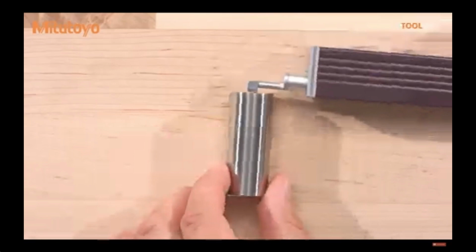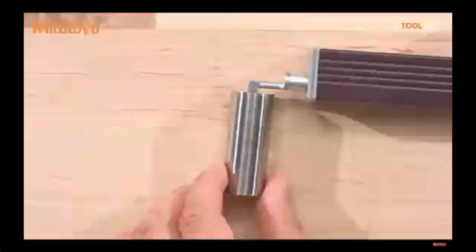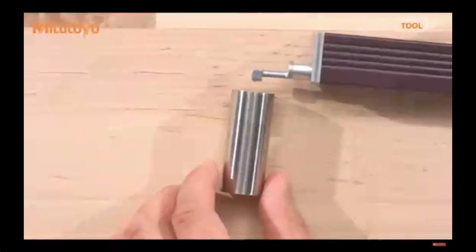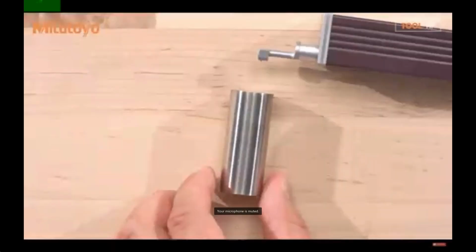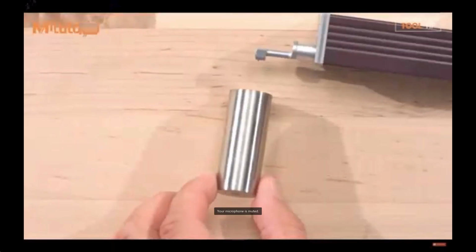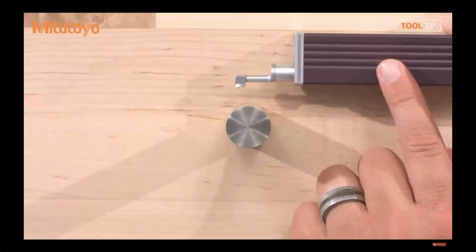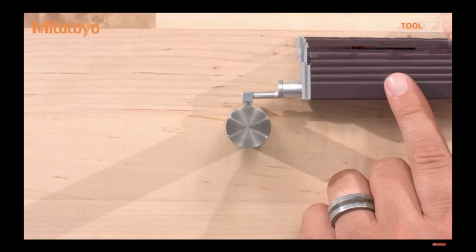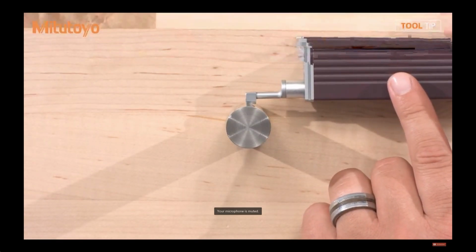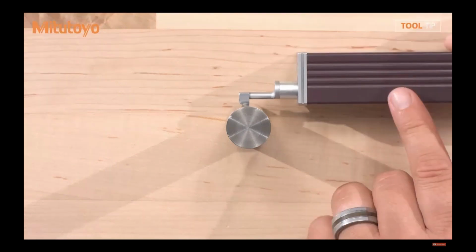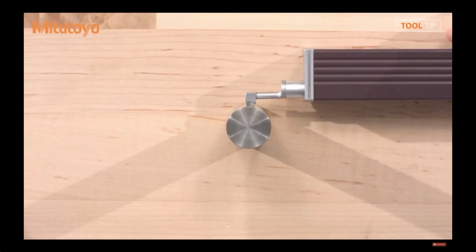If you wanted to measure the top face of this part, you'd be fine as well. What if I wanted to measure radially? That would be an issue with the skidded system. So let's flip the part up here. Now if I were to present the stylus to the area, as I move the stylus back and forth across the part, you notice depending on where I am, either the beginning or the end of the skid is going to be off the surface that's being measured. Right? I'm either going to have a gap at the beginning or a gap at the end of the measurement. Right, and this would be bad because that's the datum and it's not making consistent contact with the part.